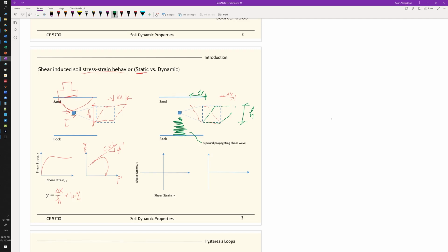So you imagine the loading adding on it. So this is the soil, right? This is your axis, and you can go back and forth like a sine wave going through it. So you could have your positive loading, and you can also have your negative side of loading. So the stress-strain plot will look like this. First, you will go positive on the stress, so this is the positive part, and then you generate positive deformations.